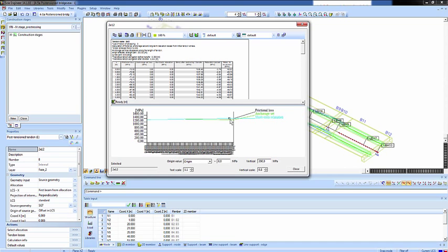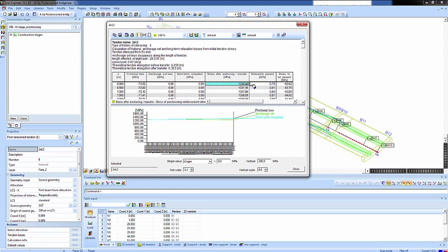And due to the friction loss in your anchorage set, you can see that the stressing is applied on the right hand side, on this side. Also in the table you can view those values. So actually at position 0 you already have loss due to friction. You have anchorage set loss, which is set to 0. Short-term relaxation, which is not calculated yet, there. And you have stress after anchoring. And the relaxation which comes is this quantity.